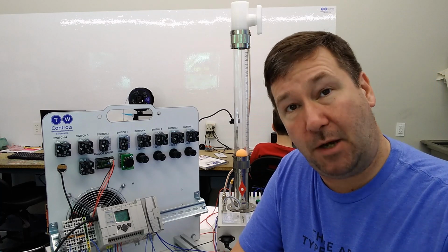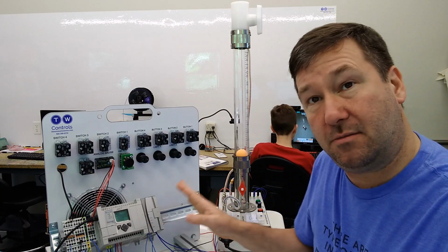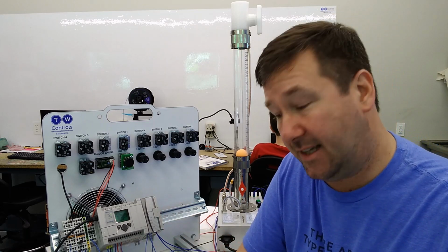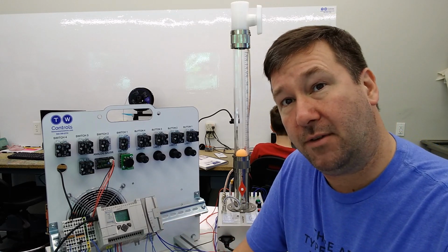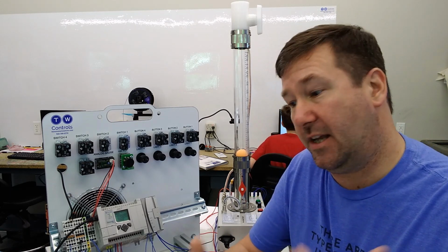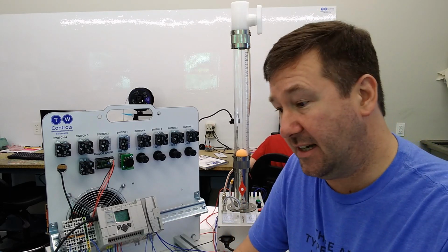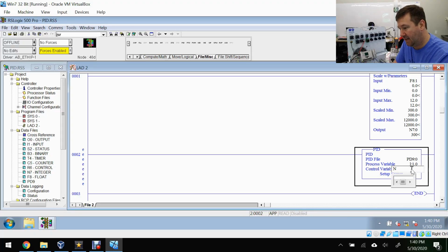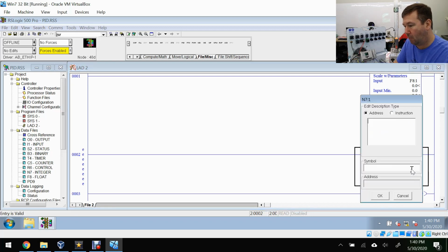Now I could just type O:1.0, which is what is to our fan speed right now, but I'm actually going to put this in an integer to start with. This is an unnecessary step for this video, but in future videos we are going to need that. So I just want to build out that structure. So I'm going to put this at N7:1, and we're going to call that our PID command speed.